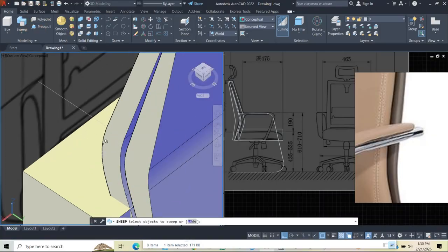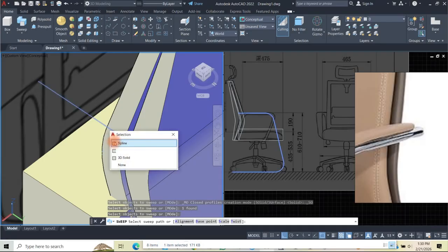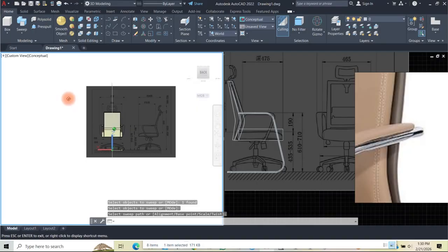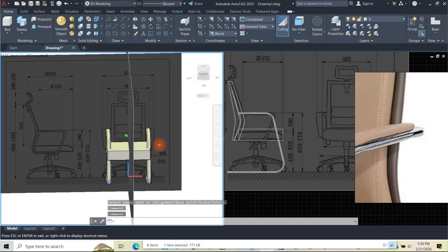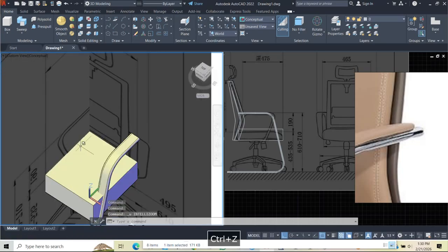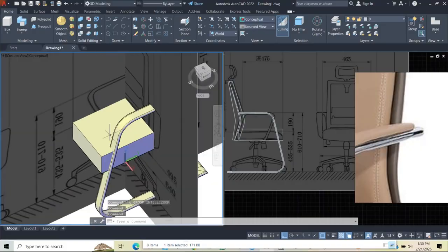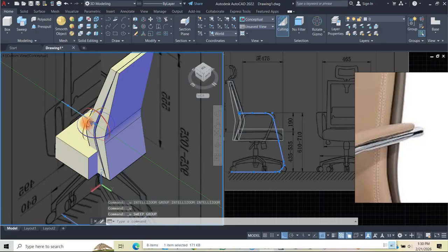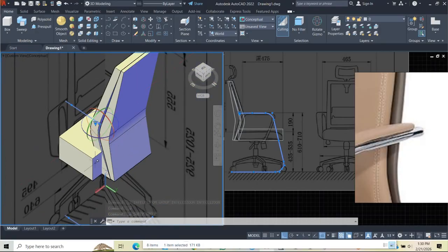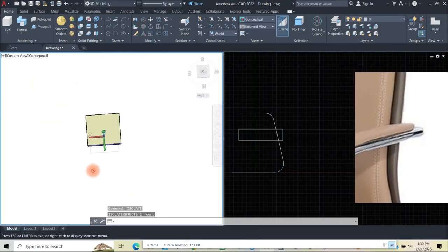So we'll go back to sweep, select this shape, enter, and then select the spline. And then it will do this, so this is still better. We can work with this, we can make do with this one. So I'm thinking I should still spread this back apart, okay? So let's select this spline, and then this mesh, isolate them so that we can move them to the side.